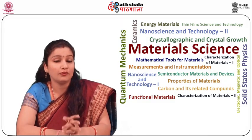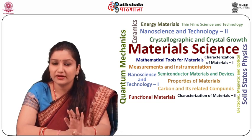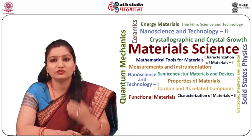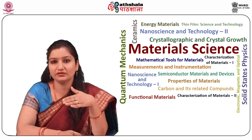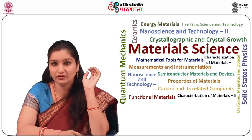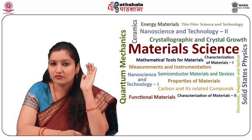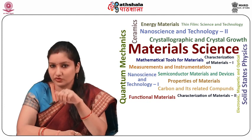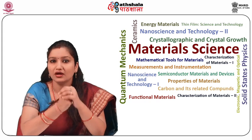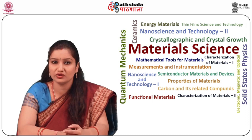Now let us study about the design for fatigue. To secure satisfactory fatigue life, it is necessary to observe the following points in the design procedure. So the first point that we need to observe in the design is to avoid stress concentration by eliminating sharp recesses and severe stress raisers, that is, the modification of design.